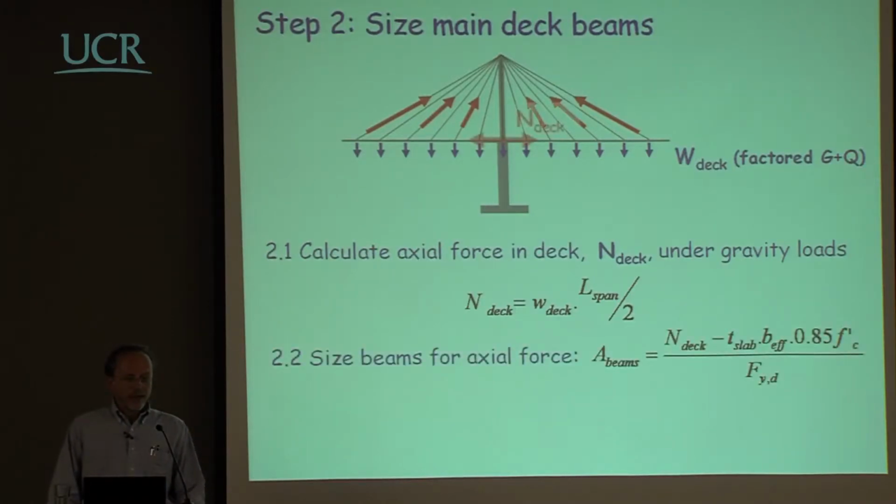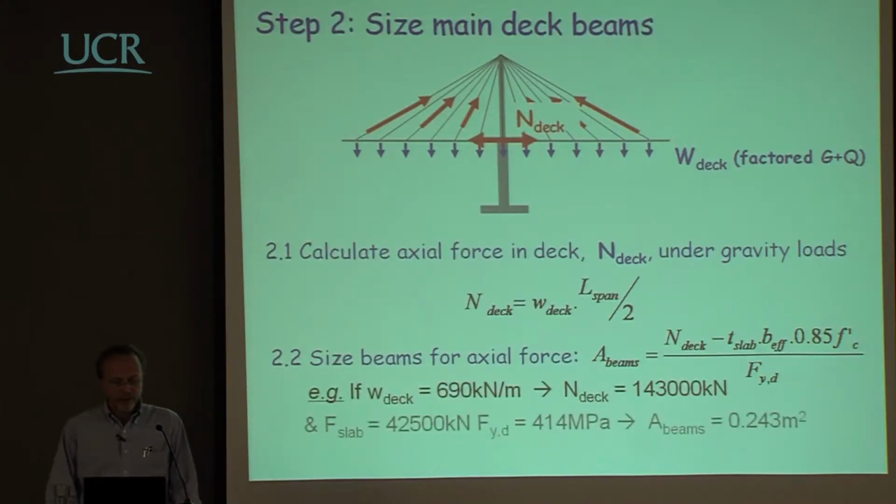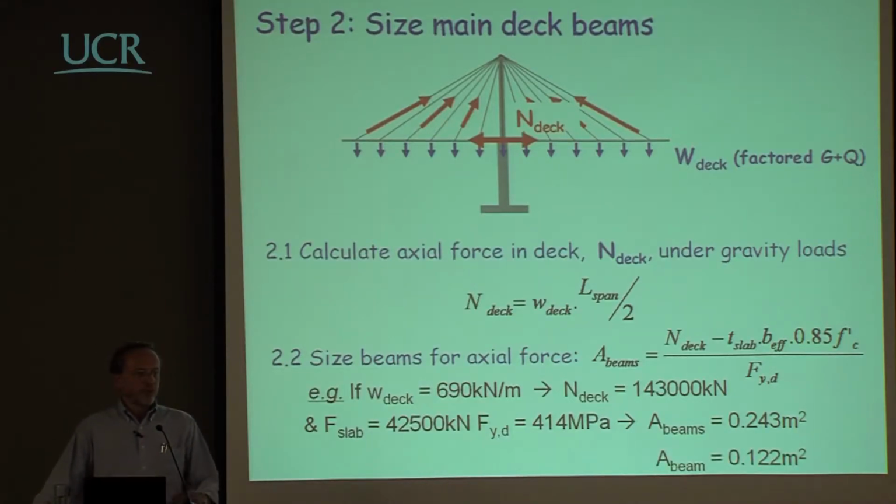And after that, maybe you will try to size the longitudinal beams for axial force. If you go ahead with the figures that we were using earlier, and you assume a certain weight of the deck, for example, 2 tons per square meter, including the live load, you end up with a section for the longitudinal beams, and this is just for axial load, not for flexion.